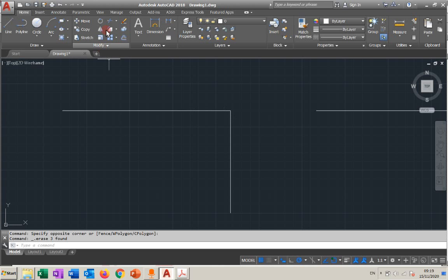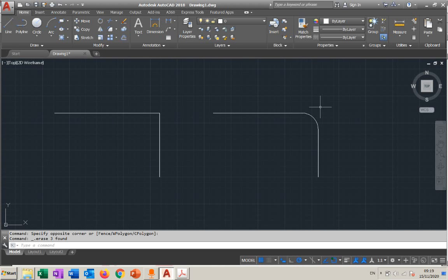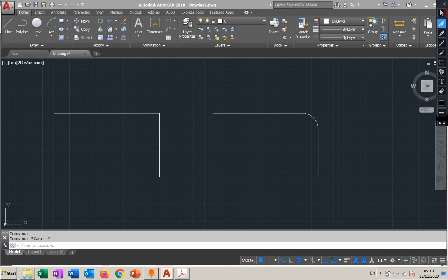So remember, if you see any round corner which you know its radius, for example, I know the radius of this one is 100, I can convert this directly to this one without drawing or finding the center. I can directly convert this corner by using fillet.